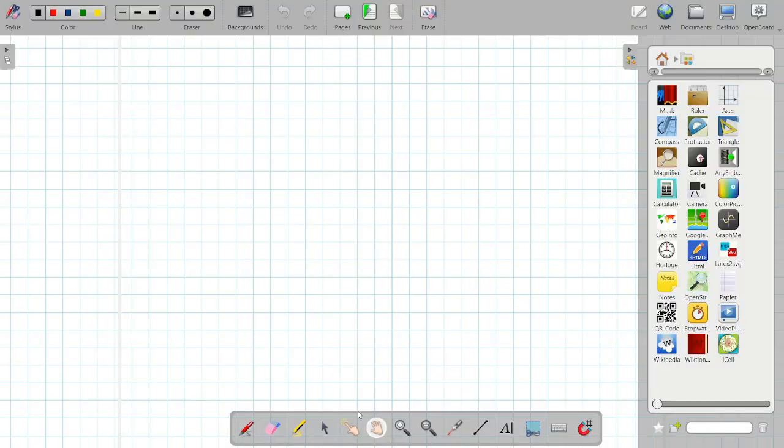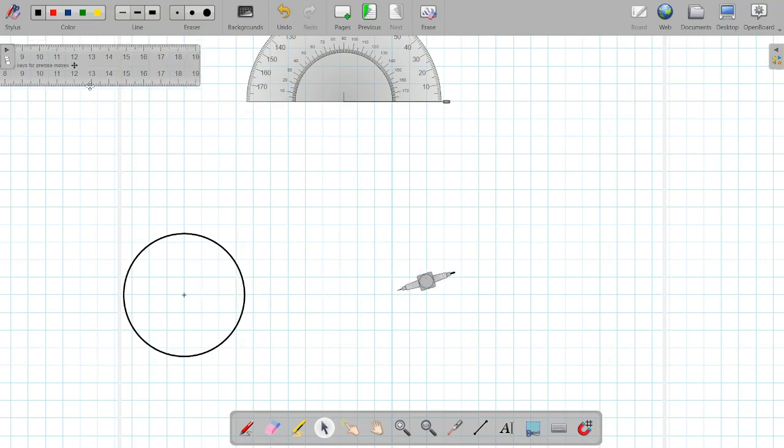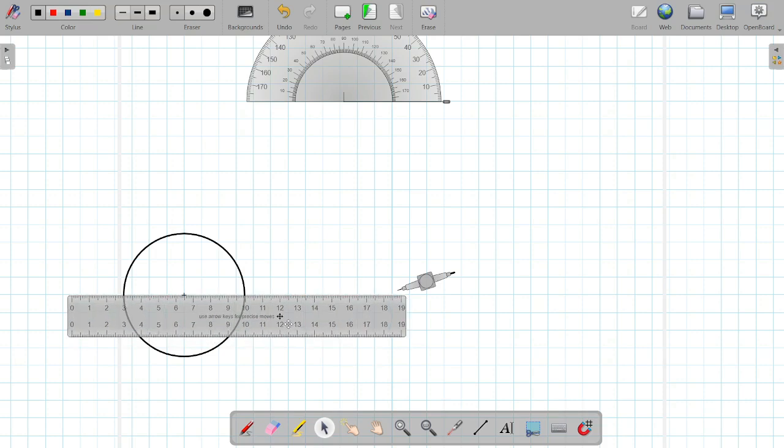So in the question it was given the diameter of the circle as 70 mm. So first we will draw a circle of radius 35 mm. Please note that in this the circle will be dark. Then, as usual, we have to divide this circle into 8 parts.